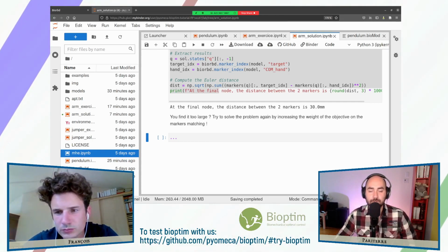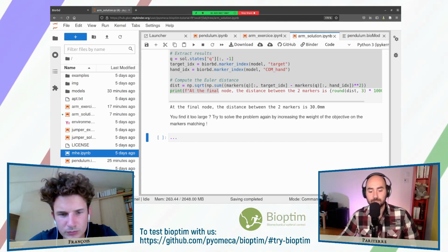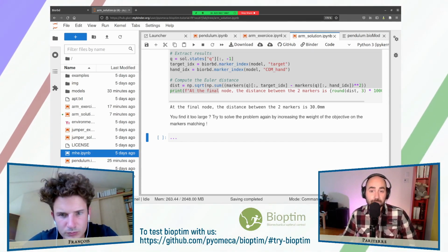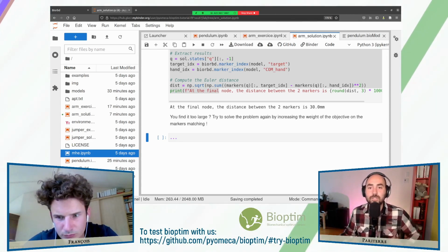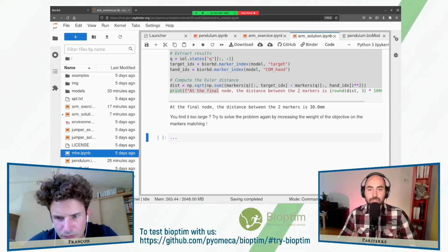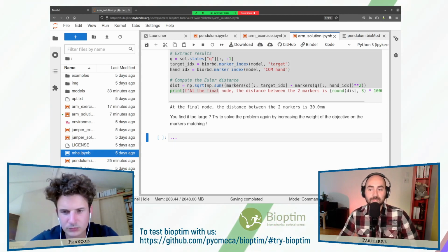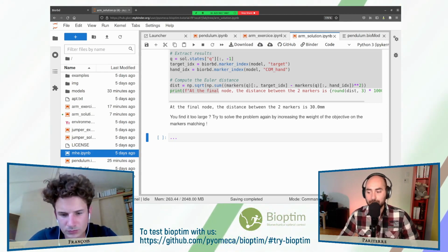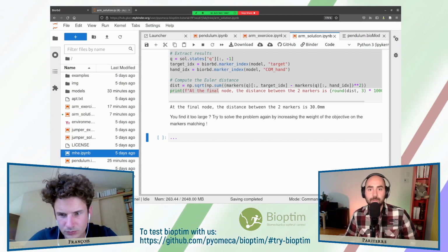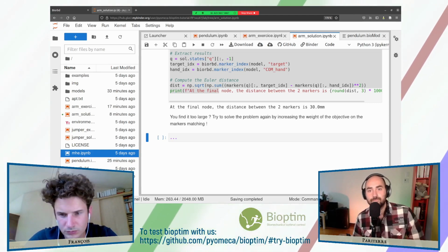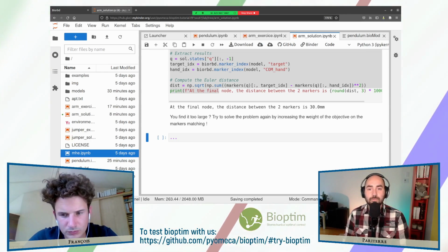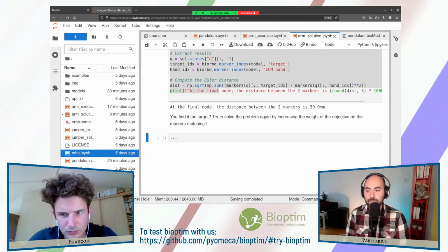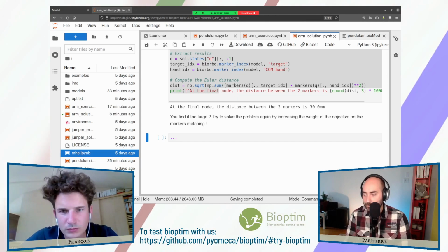If you are in multiple shooting, you may want to increase the number of shoots, or increase the number of steps between the shoots. There is Runge-Kutta 4, which is implemented, and also Runge-Kutta 8. But most of the time, if you have something that converges, you can do a single shooting and you'll find the exact same answer.